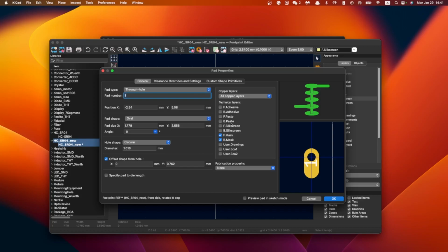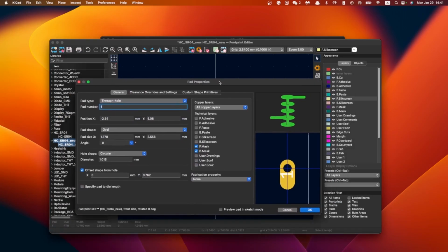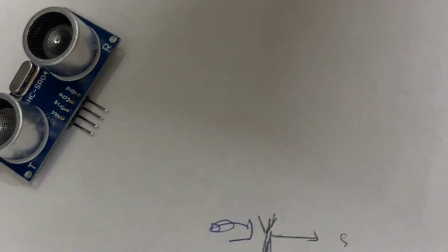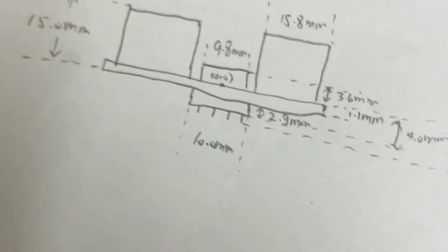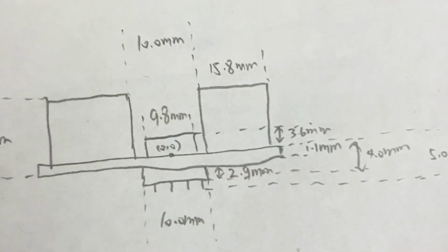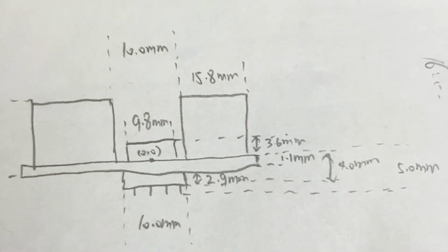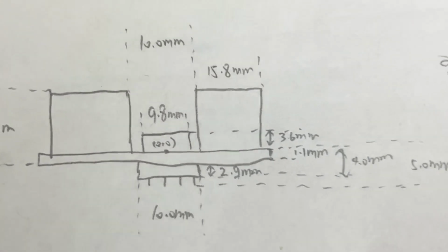That's why I can pretty easily specify the gaps between these pins without using anything to measure it. And there's also one thing that's pretty important, which is to specify a point zero or an anchor on your sketch here. And as you can see, this device is symmetric.